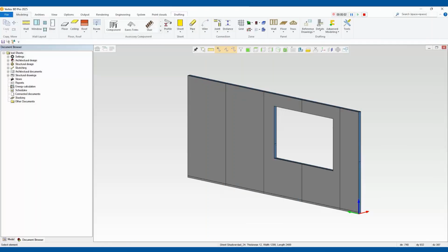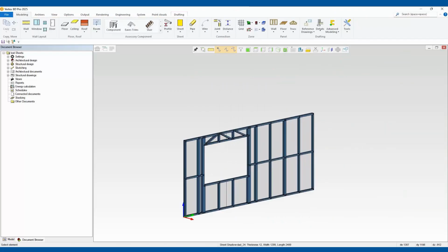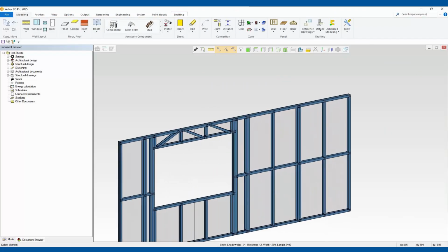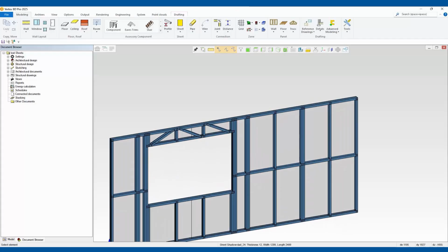Okay, so we're going to go through adding sheathing to a wall, this vertical cladding, with a view to creating these double studs, so you've got something to fix them to. This is slightly different to cladding.